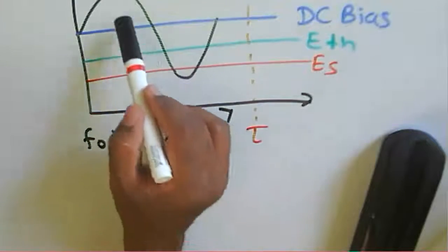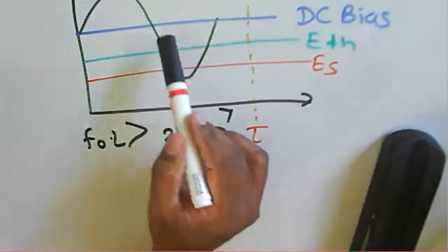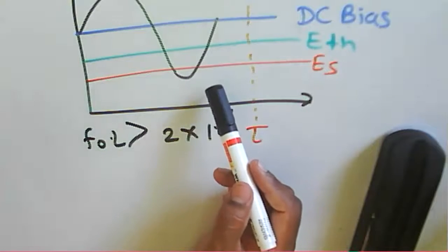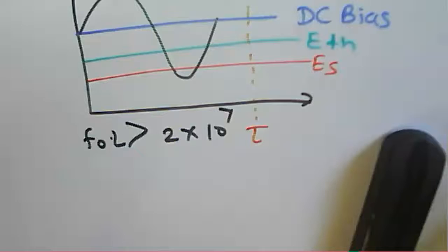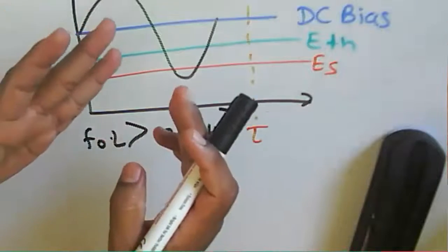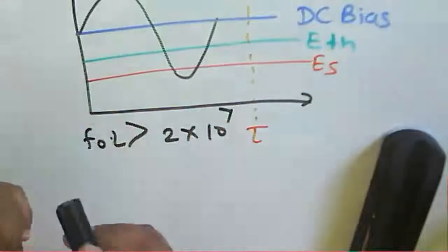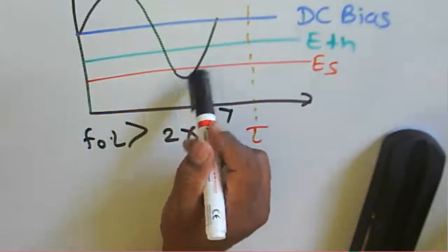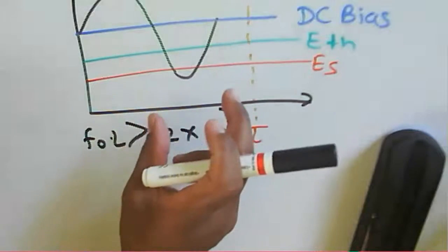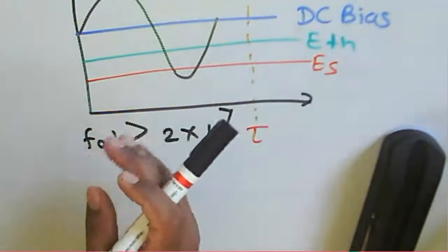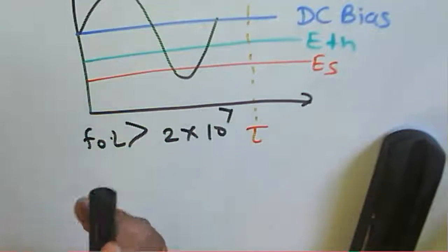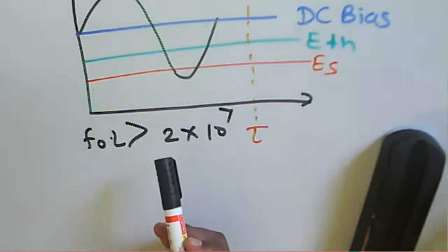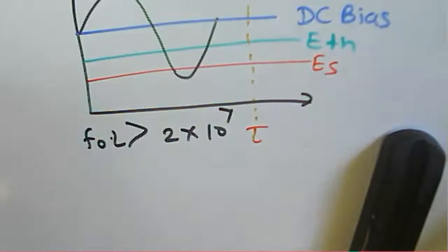This happens in the negative half cycle. This one is about a positive half cycle. This happens in a negative half cycle. And because of this, what happened here? The domain collapses before collection at the anode, because of this drop of the bias voltage. Again, when the field rises above this particular threshold value, a new domain starts forming, and then this process repeats.